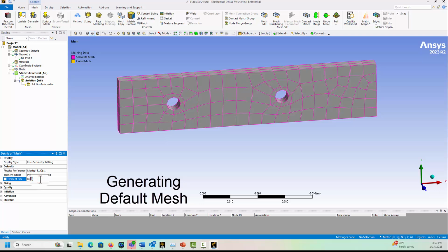So I put a 0, I put it back to default. We'll leave it at default initially so we could solve and make sure everything kind of looks right, and then we'll get our mesh. It's nice to have a quick solution while we're trying to figure out our boundary conditions initially.